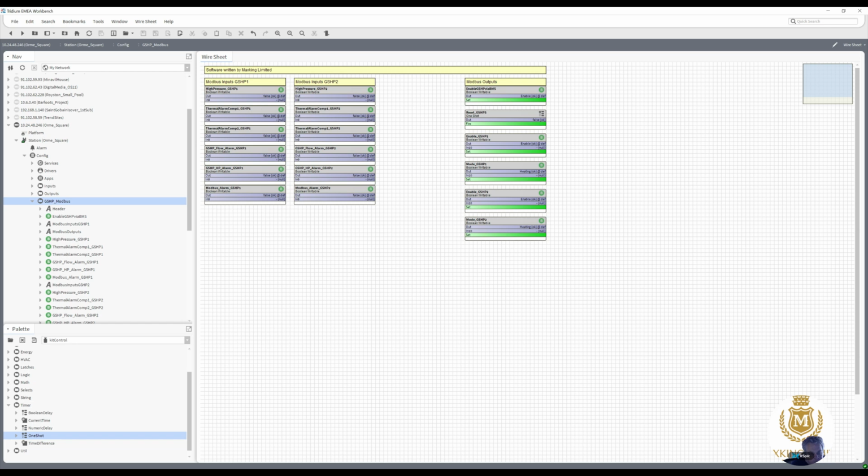And then for the outputs, we've got enable the ground source heat pump via the BMS, because apparently it needs that. But again, I'll check it when I get to site. And then we've got the reset the ground source heat pump, so we can send a reset alarm. I've just used a single one shot there. And then enable ground source heat pump 1, which will be tied into my logic.